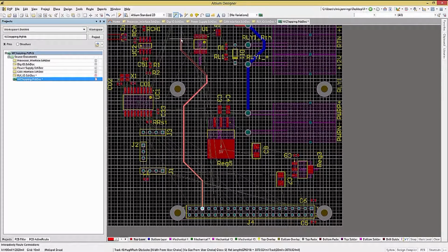What if during your routing you want to back up on some of the placed track vertices? Hitting the backspace key will remove the last placed endpoint. Continuing to hit the backspace will sequentially remove the remaining endpoints back to the starting point. This is helpful if you need to revisit the track routing after having placed some of the segments but have not yet finished the routing.